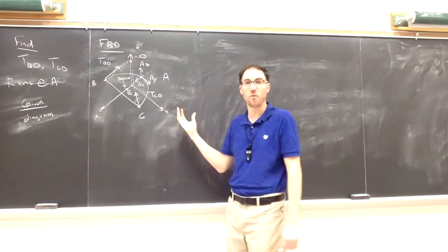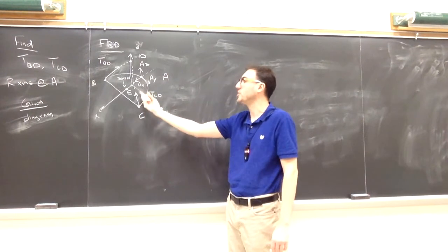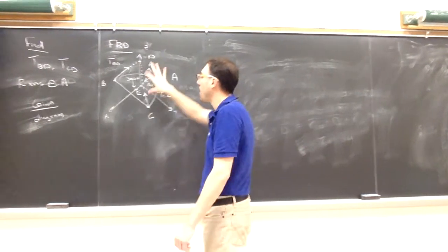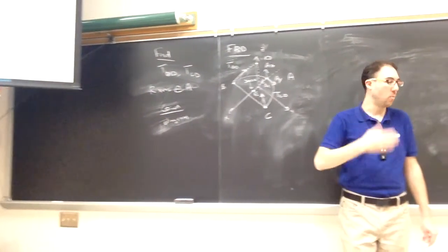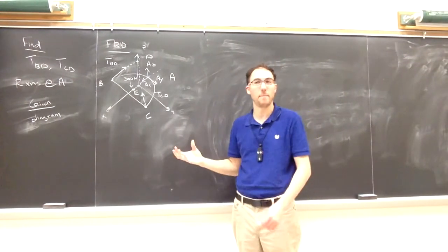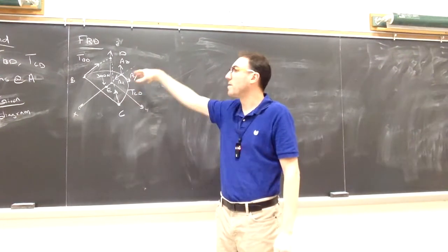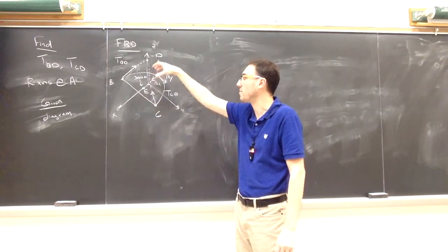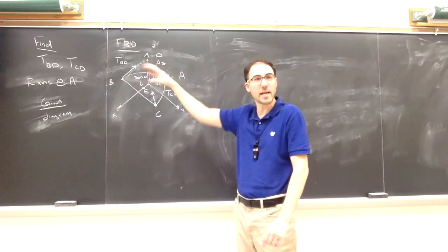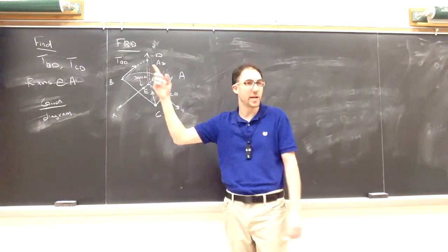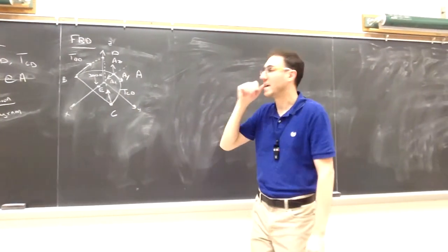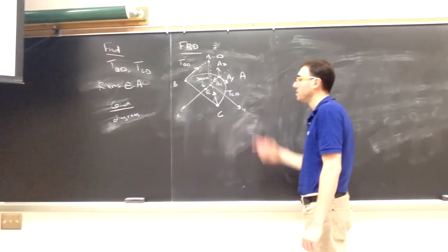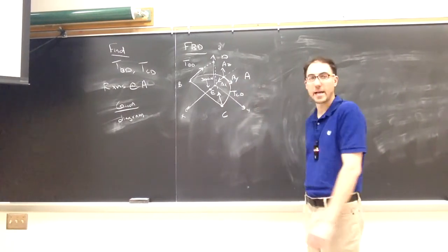If it were, again, a normal force where it can only be pushing, or like this tension, I know the tension can only pull. Those directions I am certain of. Now, as far as rotations go at A, or what, if any, rotations are prevented because of that ball and socket connection at A. We can rotate around Y at A at least a little bit. Eventually it's going to prevent us, but we can rotate it somewhat around the Y-axis. And around the Z-axis, again, we can rotate it that way too. So all rotation is allowed at least a little bit at A. So because all rotation is allowed, then there's not going to be any couples acting at A. So we only have those three forces, no couples at A.